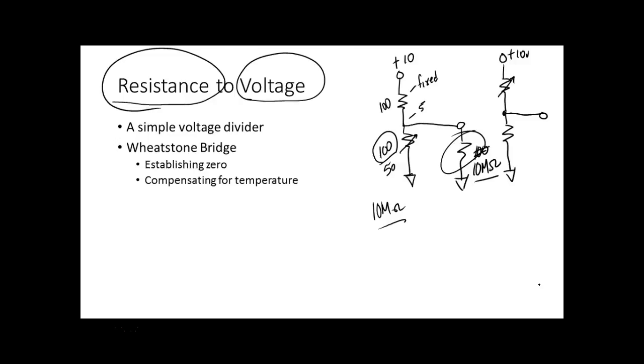And one of our guys went into number 4 galvanizing line, and he wanted to measure the output of the mag amp. The mag amp was sensing too much current. It was a safety device trying to sense if the motor was pulling too much current. He put his meter in parallel with that mag amp, and what did he do? He shut number 4 galvanizing line down just by putting his voltmeter across a high impedance circuit. He halved the resistance, the mag amp put out the wrong voltage, and he shut the line down.